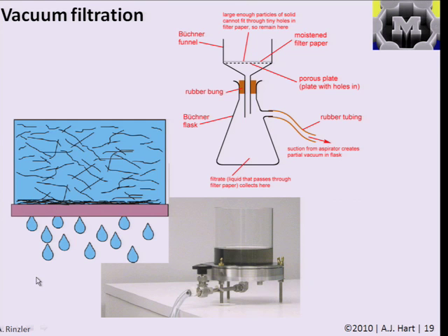Another method that can be used to create a tangled film of structures, in addition to spin coating and dip coating, is to filter a dispersion of structures by a vacuum method. This is what's called vacuum filtration. What's done here is simply you have a pot, like a glass bin, containing a dispersion of nanotubes or structures. This is probably carbon nanotubes functionalized with a surfactant like SDS.